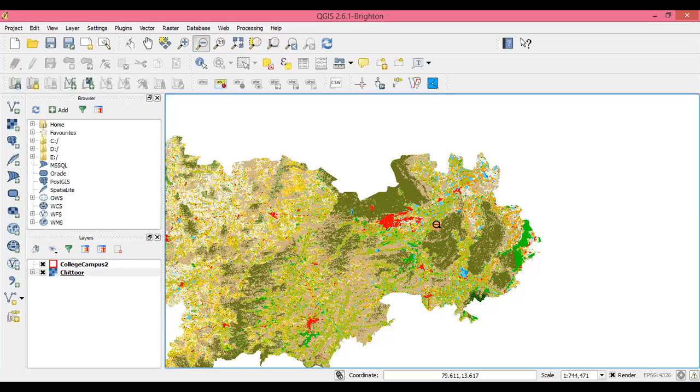We've given you one empirical equation, the Kirpich equation, which gives you the time of concentration in the watershed, given certain parameters. What are those parameters? Slope. Say that again, one by one. Slope of the catchment, then the longest distance that has to be covered. Okay, so let us try to understand how to find those out.